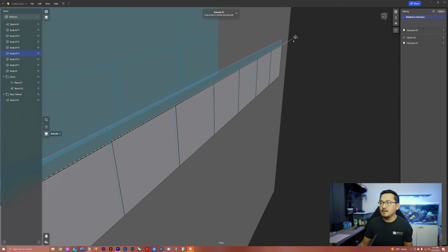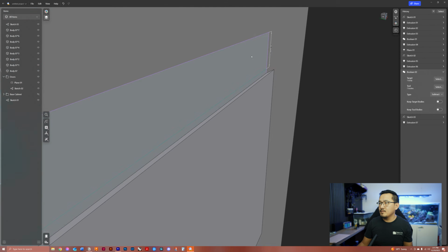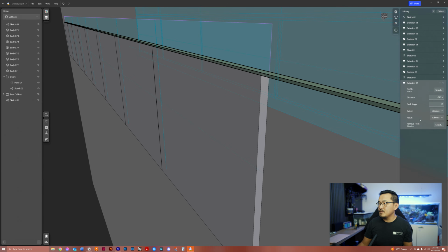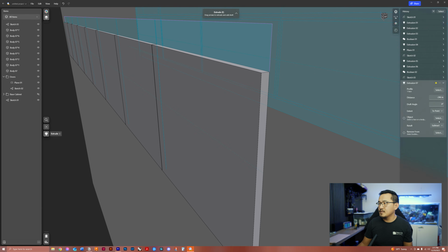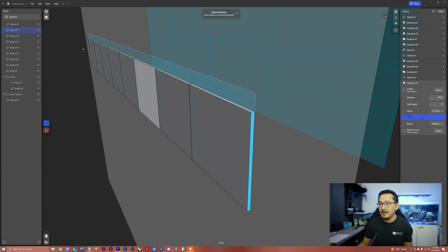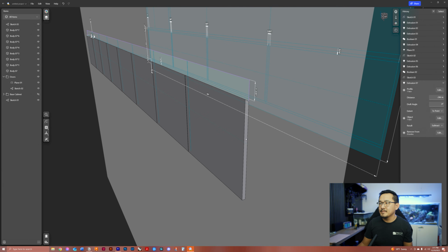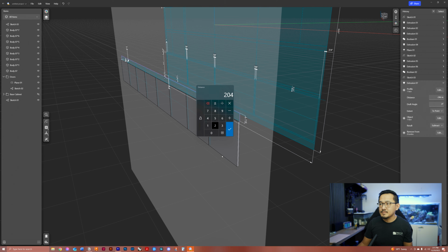all the way over. And what we'll do is go back to our history, open up that extrusion, and we're going to change our distance to point. Our point will be the end panel, right? So no matter how long this thing expands, this extrusion will always be tied to this end panel. So now let's verify that.